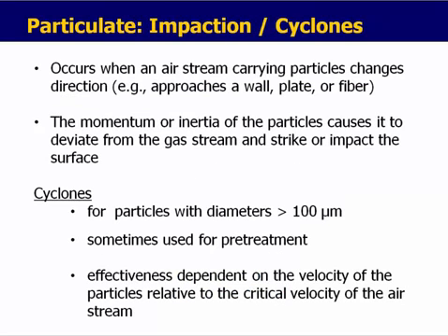The second method is to use impaction or centrifugal force to remove particles in cyclones. The principle here is that an airstream carrying particles changes direction. As it approaches a wall, plate, or fiber, the momentum or inertia of the particles in that airstream is different than the momentum of the gas stream. The particles strike or impact the surface and fall down.